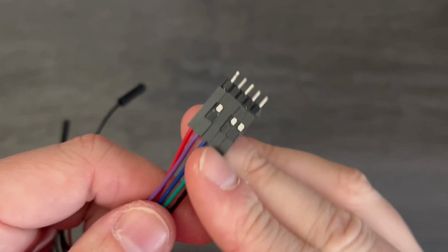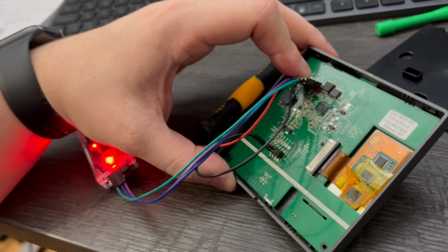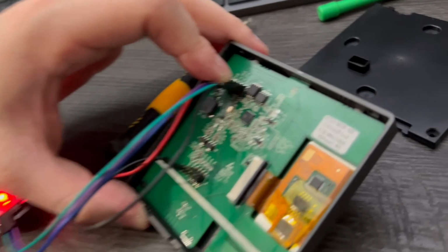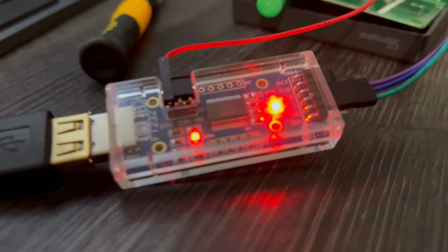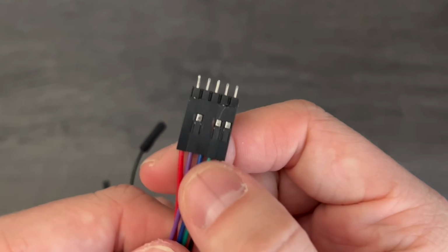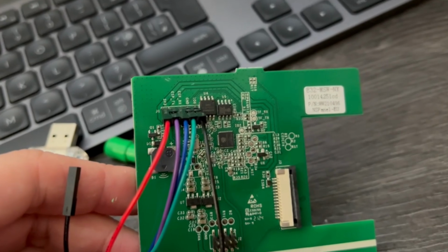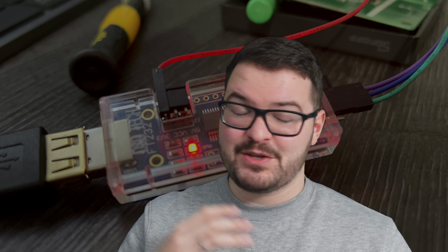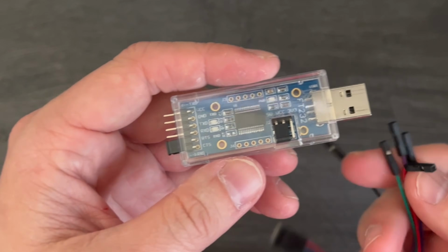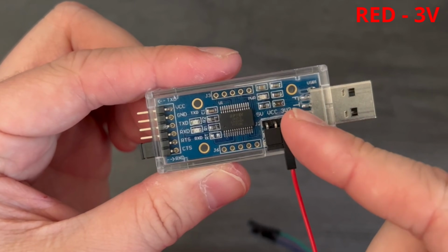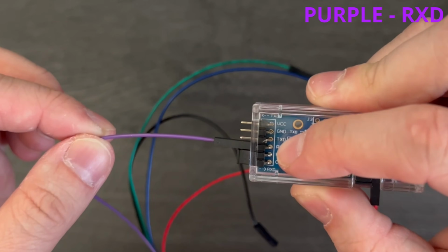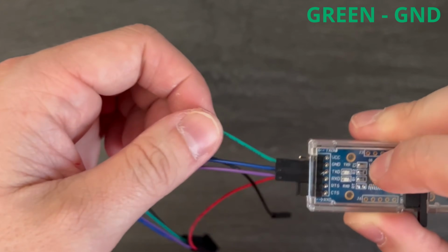and it just saves them wiggling around or moving out of place, which is something that you don't want to happen whilst you're trying to flash something. I definitely recommend trying to hold all of the wires together, and if you do decide to make use of something like that header offcut, then you should end up with 5 wires all held together like this. So let's attach the wires to our adapter, and there's no real colour convention for these wires, they're just wires that I had lying around. So here I'm attaching red to 3 volts, purple to RX, blue to TX, and green to ground.